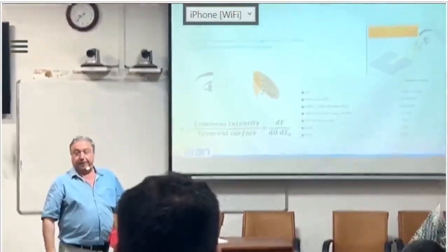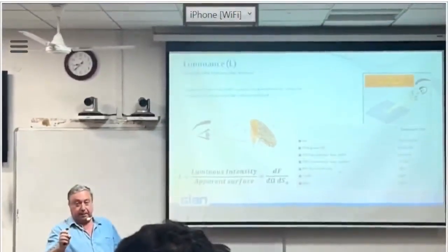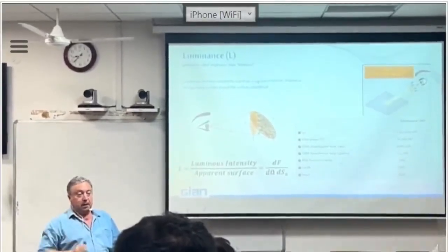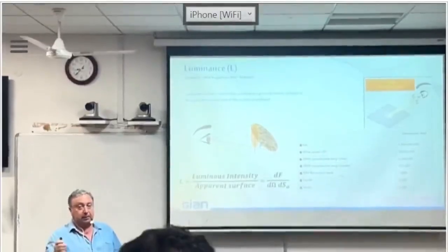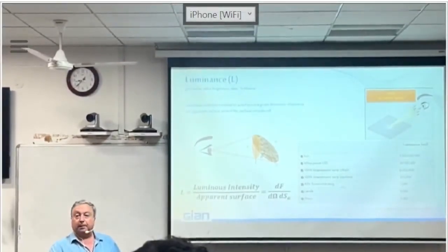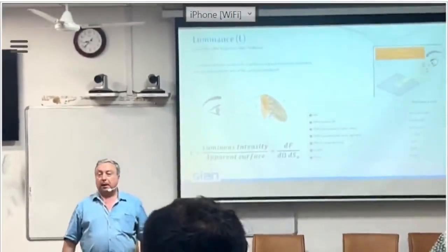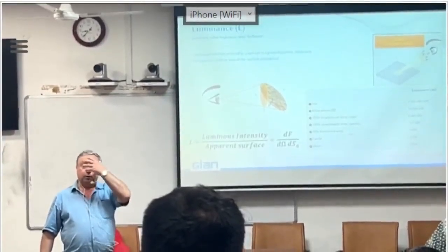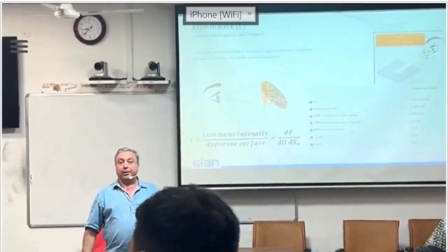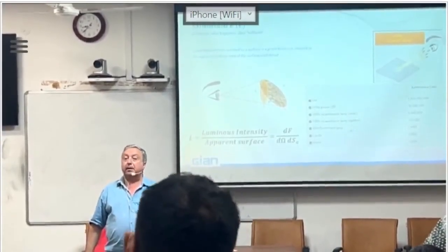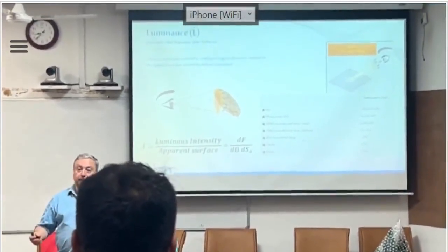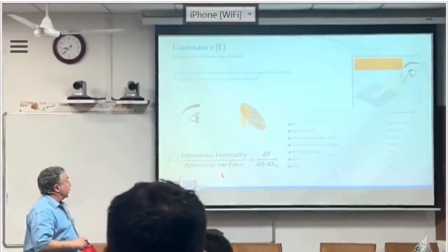That means the smaller the object that emits light is, the higher the brightness is. And the higher the brightness is, the more this attracts your eye. This is an automatic mechanism of human beings. We are looking for the brightest source. And if the brightness is higher than 10,000 candela per square meter, then you are glared, and even if you close your eyes, you continue seeing a phantom image of the source, and this is a very bad point when you illuminate something. Well, let me give you some ideas.